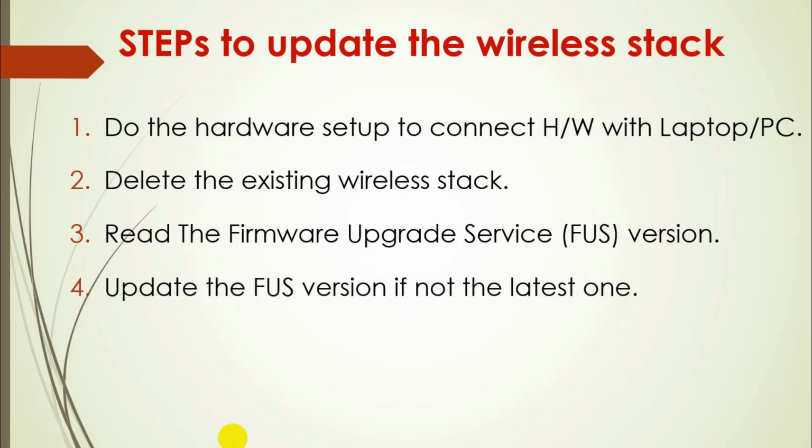Then you will do the FUS update. If it is already updated, you don't need to do it. If it is not, you need to update to the latest firmware. Then you will do the wireless firmware stack update. After this, if you want, you can also update your application code using the same method.